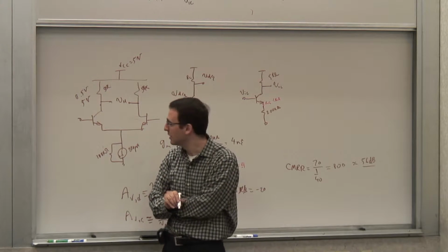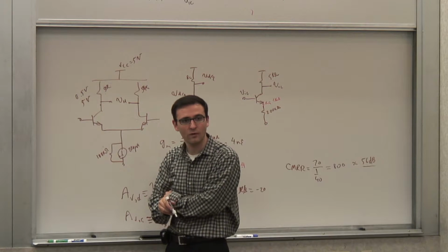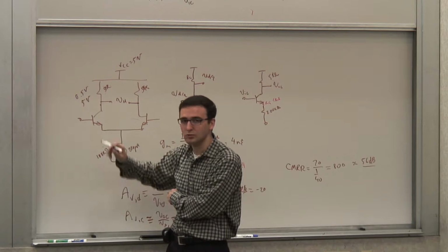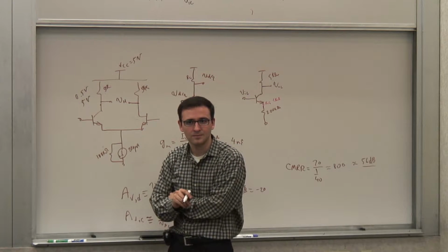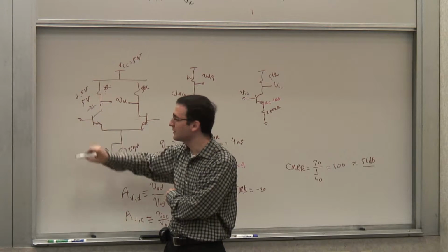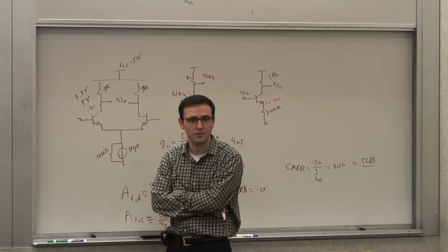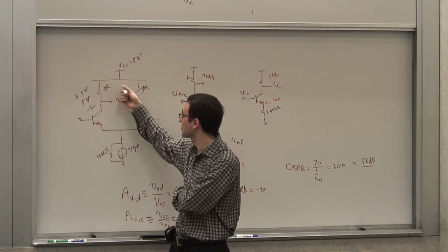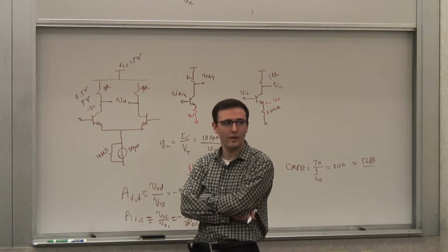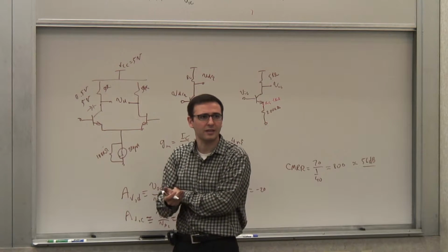So it means that this voltage is what? 0. So if this common mode voltage is higher than that, let's say it's 1 volt, if you set it at 1 volt, can this go to 0? Before it hits 0, around the time it's kind of 0.3, this side is forward biased. So this transistor actually can go into saturation, so you have to be very careful about that. If you make this resistor just large like that, at some point your stage will saturate. The way to avoid that is either by having a larger VCC or keeping this voltage at a lower voltage. You're basically running out of headroom.